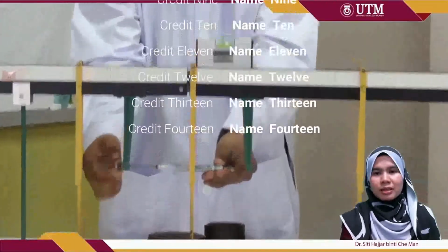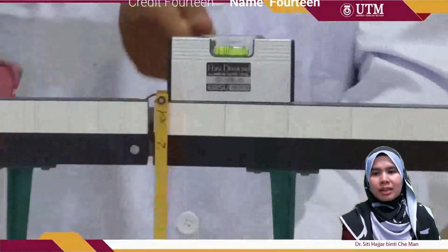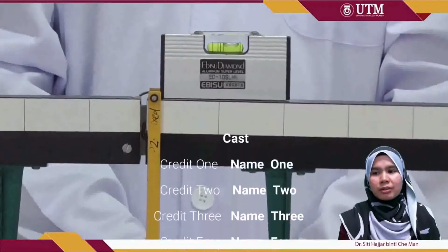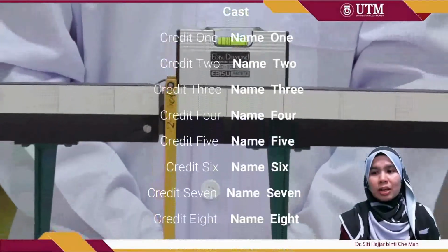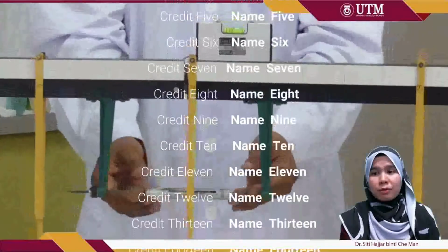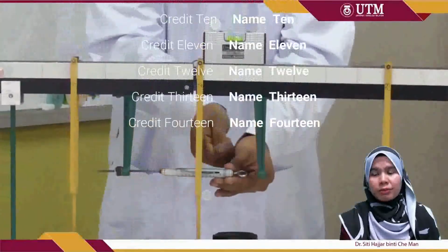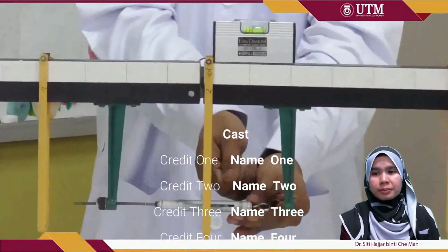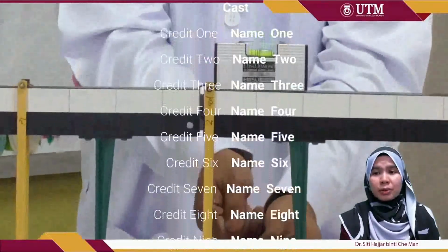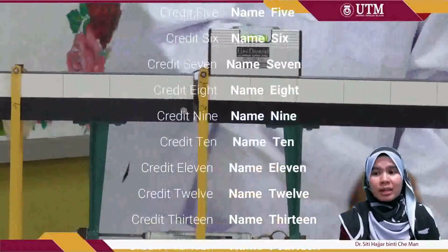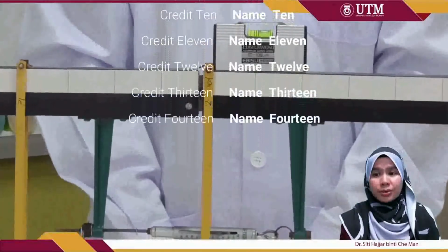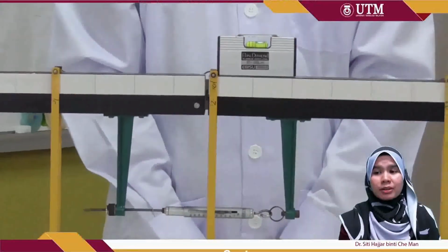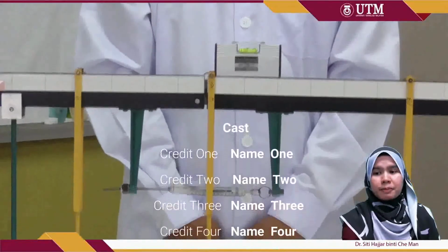Now, as you can see, the bubble is at the center, and take the initial reading from the spring gauge and jot down in your table 1 for the zero load column for all P1, P2, and P3. The reading just now will be the balance reading, and the net force for load is 0 as no load is applied on the load hanger yet.